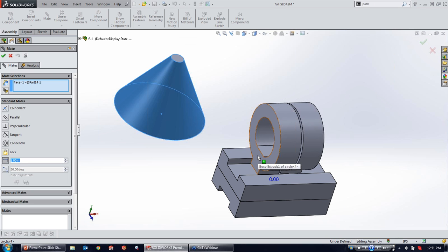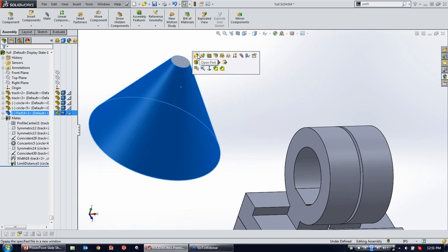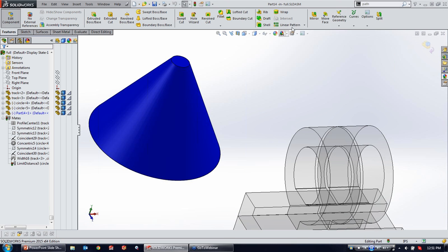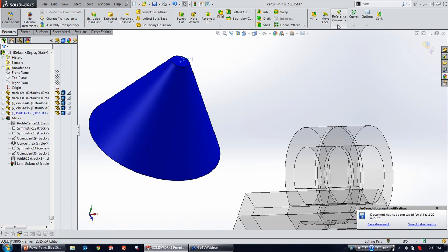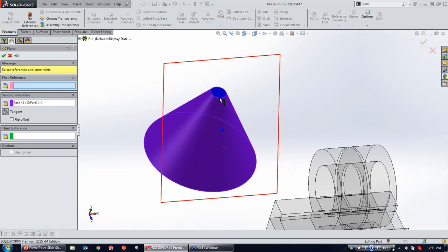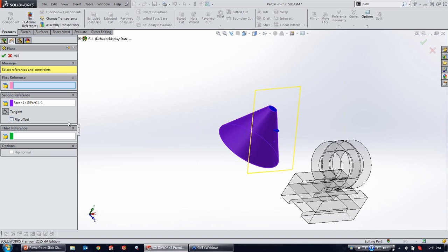For a rounded edge, what you'd end up doing is creating a plane. So if I selected a point where I want a plane, I can do it that way. So let me edit this part. And go ahead and throw a reference plane on there, or even a point. So if I know the point that I want to go through is here. Yep, that looks fine. Now I want to do a plane based on this and going up through this edge, which I can't do. A tangent plane running through there. I thought that would work. That's a good question, John. Let me do some digging, and I'll get back to you. So it's a distance mate from a tapered edge. Yep, I will respond to you there.